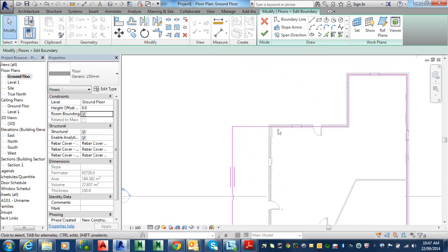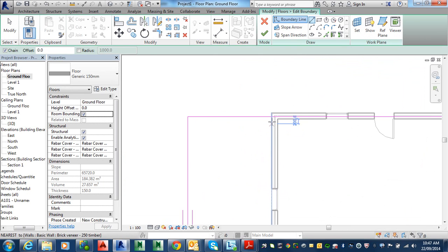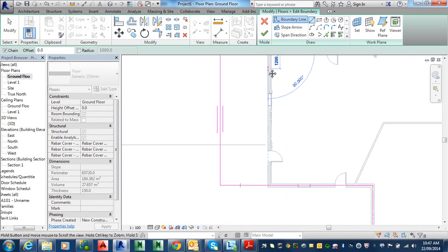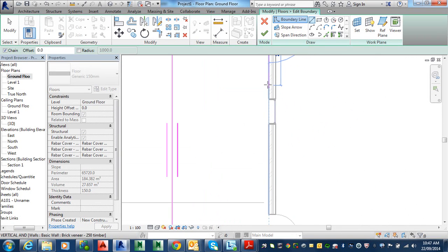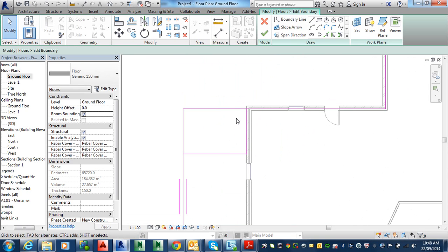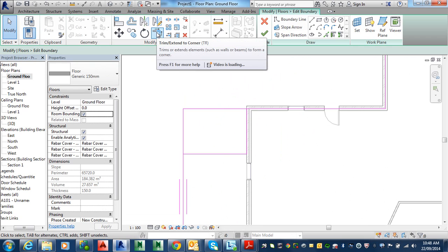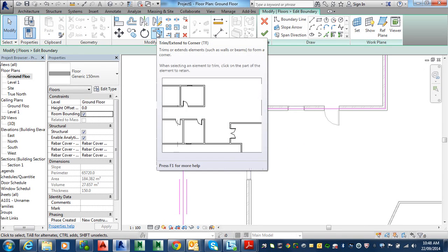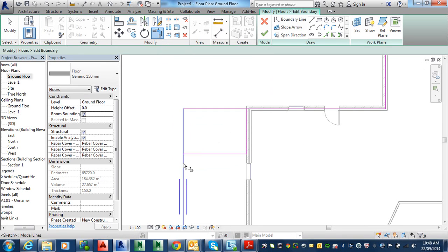Similarly, that's fine. You might not want it the full length though. You might not want it all the way down there. So you just draw another line. Just pick the line command and say, okay, I'm going to draw a line from that corner there to about whatever you want, say, across there. Then you use what I call the fillet command, which they call trim extend in here, because I use the AutoCAD terminologies.